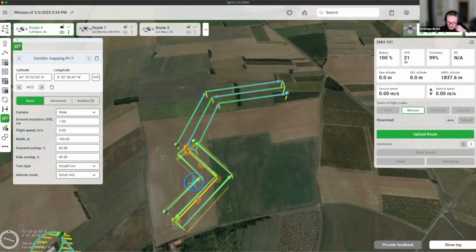Yeah, if you're using the Mavic 2 Pro, then you can use UgCS for DJI app. But maybe just to explain a bit better: the flight planning, no matter what drone you use, you do on the desktop version of UgCS. And by desktop, I mean you can of course have it installed on your laptop. So guys have it on laptops, on office computers, wherever it's more convenient for you. And then simply you connect through the mobile app. In the case of Mavic 2 Pro, this is the UgCS for DJI app, and then you can upload the route there, or you can simply save it into the local storage, and then once you're in the field, you can just fly the drone.